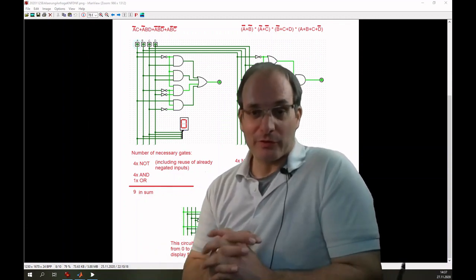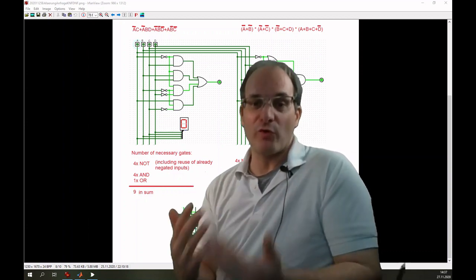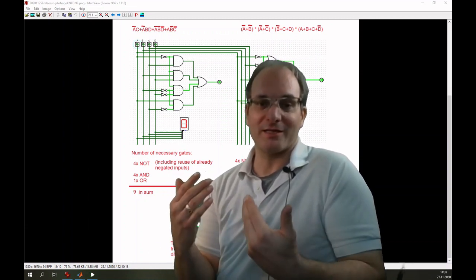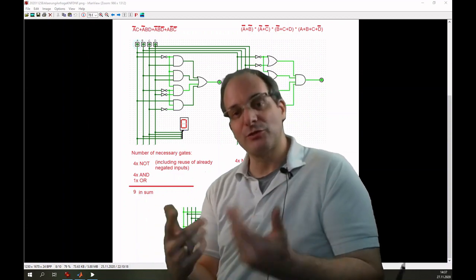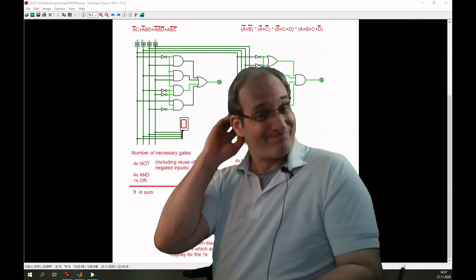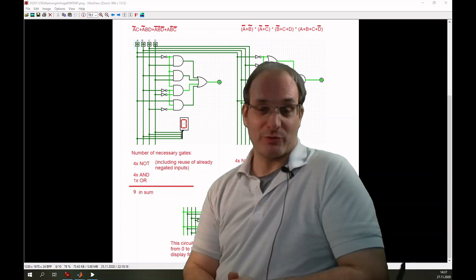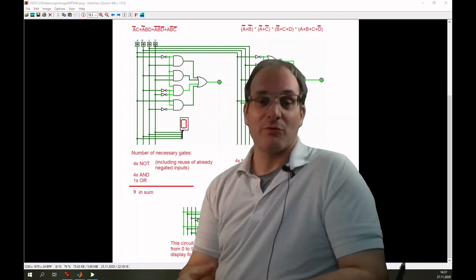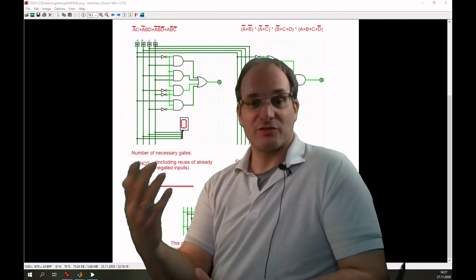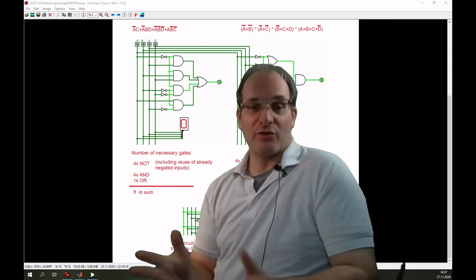And of course, usually if you want to do a real world scenario, so like shown in my sample, where all of the numbers are used, so that you have 2 7-segment displays, one for the 1s and one for the 10s, then of course you have to take care of all of these inputs, and you have to continue from 10 with 0 in the 1's position, 11 is 1, 12 is 2, and so on, and in the 10's position you have the 1 all the time.